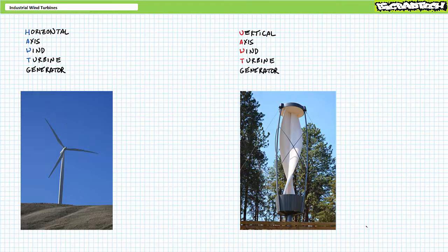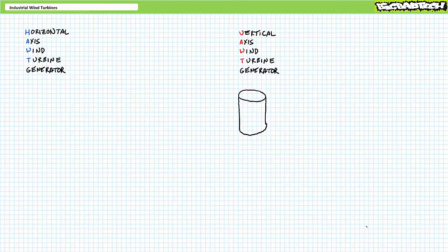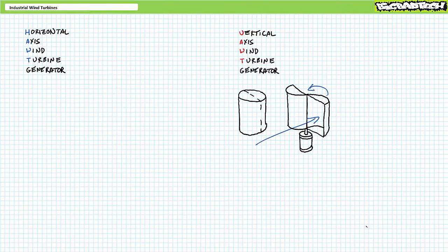As an illustration of this process, imagine taking a 55-gallon barrel, cutting it vertically in half, then gluing the 2 halves offset from one another, then installing this assembly onto the vertical shaft of a ground-mounted generator. When wind from any given direction strikes the generator, the concave side of the barrel captures the wind and the convex sheds it, such that the wind turns the generator shaft, and with sufficient speed and torque input, the generator produces electrical power output.